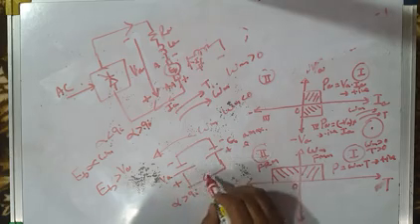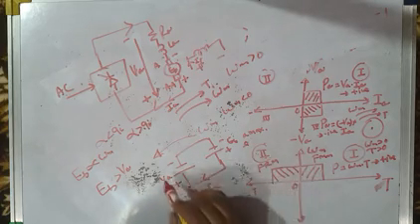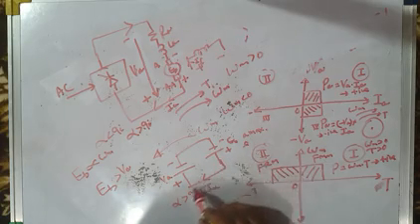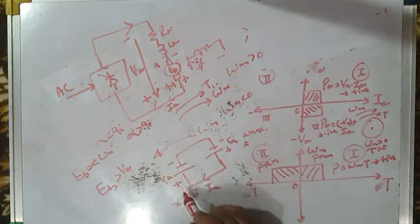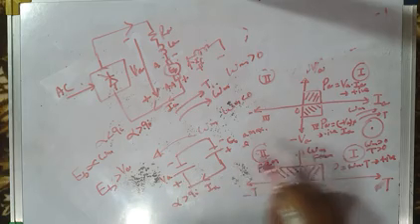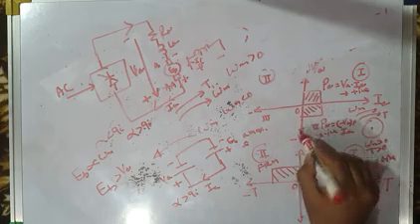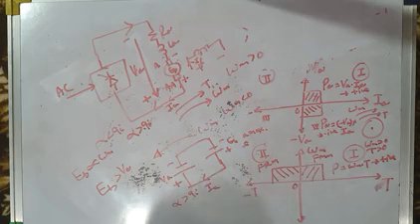And that is the case, the current flows like this. Okay. Now you can see current has become negative, it is flowing from EB to VA, or in other words, the average output voltage you have made negative. Your converter is again operating in the fourth quadrant because the average output voltage is negative, and in the fourth quadrant we are operating in the regeneration mode.